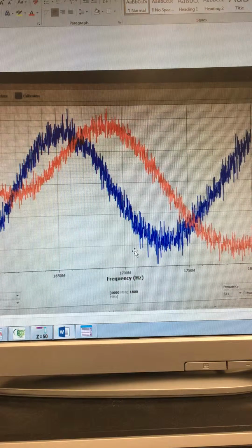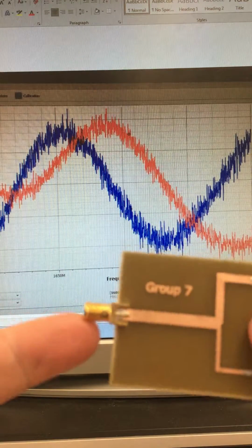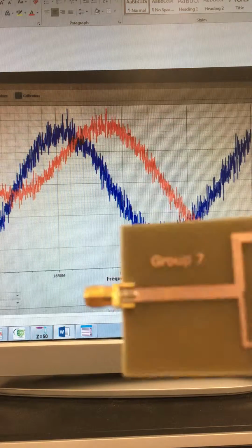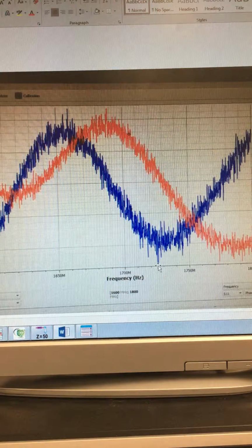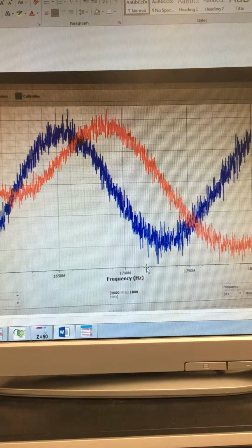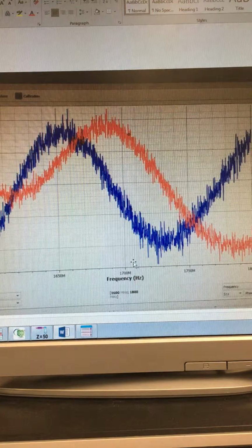the matching frequency always shifts during fabrication, probably due to the fact that the simulation doesn't include this SMA connector. It can often shift the frequency of the design. As you can see though, because it is minus 26, it is an awful lot higher than the simulation results.